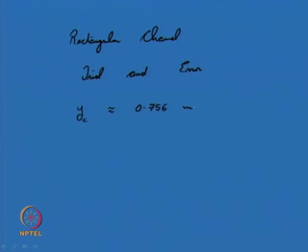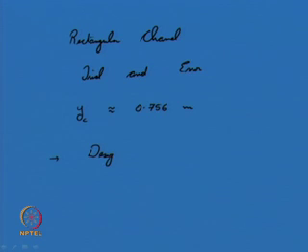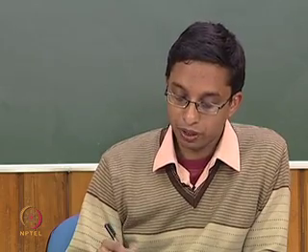The same problem you can again solve using the design curves or design tables you had developed. We had developed the non-dimensional graph of section factor versus depth of flow. Using that for the rectangular channel, you can again solve the above problem.